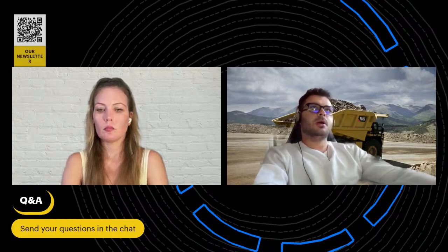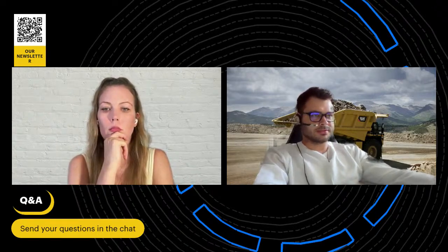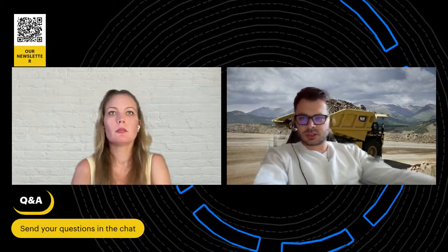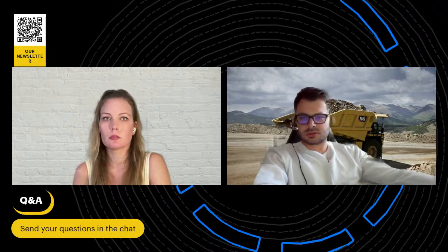You should also avoid the horizontal intersections that we tried to prove to you during today's stream. Then it should be a straight slope during the haul road. And what is the most important, I think, for a mining engineer during construction of the road is that the engineer should clearly see different mining phases. I mean, different pushbacks. Different pushbacks should be connected together with these roads. There shouldn't be any gaps, because in this case, the mining will just stop.